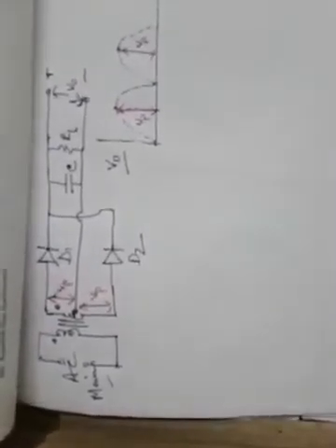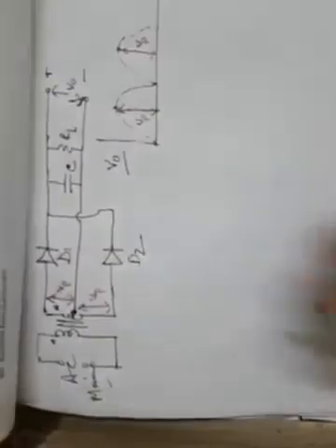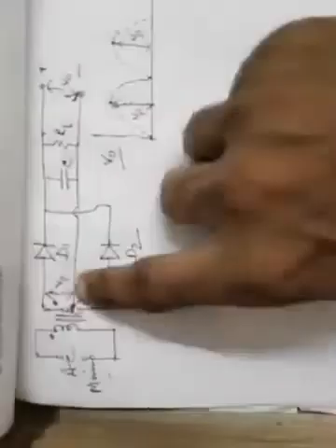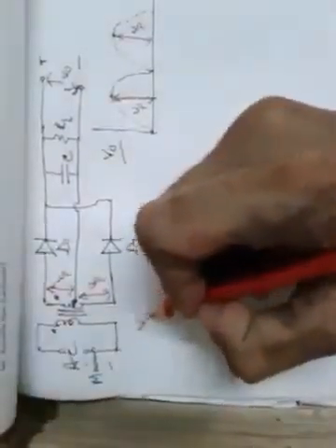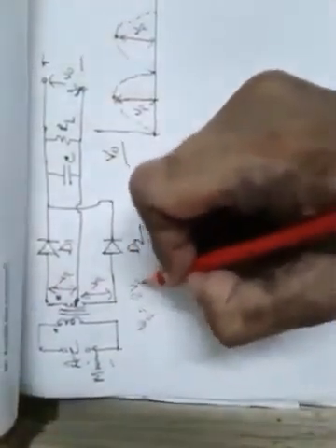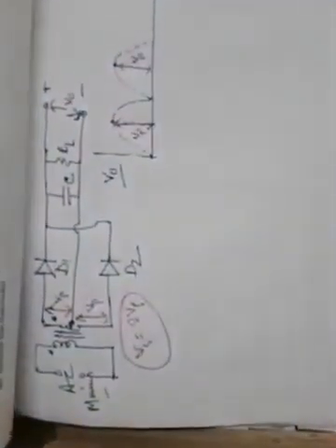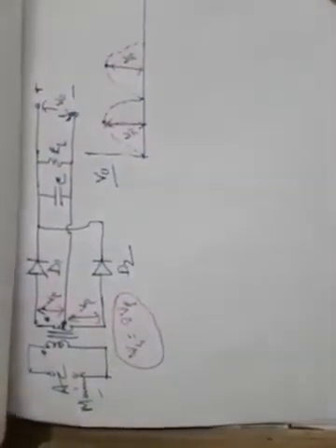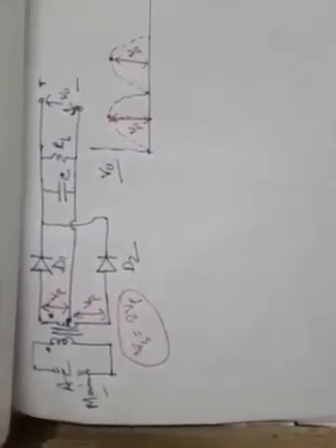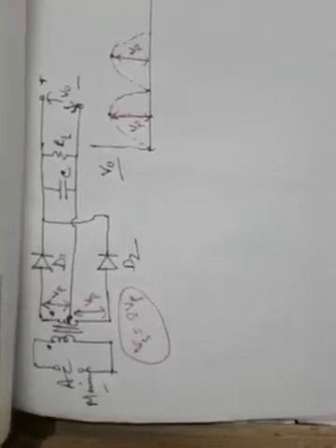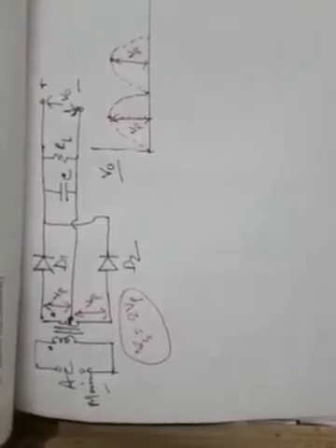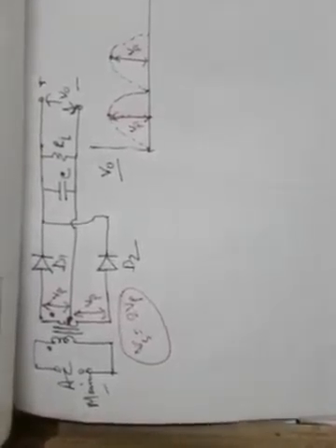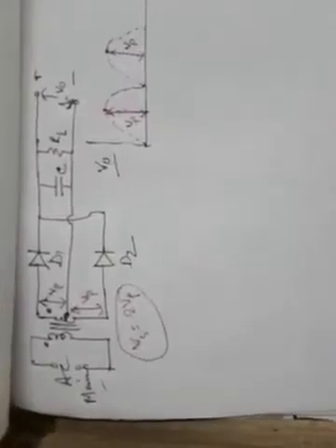So during the second half cycle, because of center tapping, this Vp is getting segregated. So actually if we consider this whole as Vs, then this Vp and this Vp, Vs is equal to 2 Vp in this case. This is very familiar to you from my lecture on this topic in one of the previous videos. Now this will happen provided the voltage drop across these diodes is negligible and they are conducting ideally.